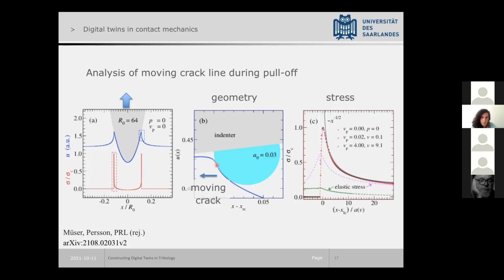And basically what happens is when a point within, let's say, a time delta t has to move down a certain distance, that distance basically diverges in the continuum theory. So this profile would be a square root in continuum theory. When you take the derivative of that, you get the velocity under quasi-static motion, and you basically get diverging velocities at the opening of a crack tip.